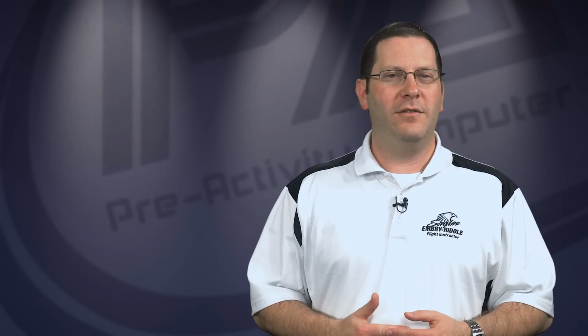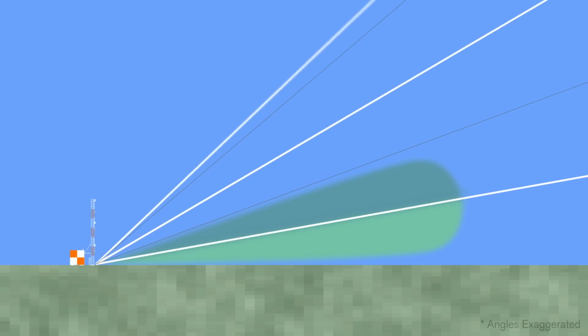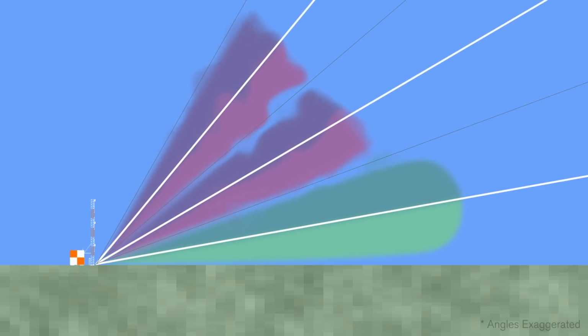Glideslopes are normally usable up to a distance of 10 miles. The Glideslope antenna creates mirrored transmissions of the true Glideslope, which produce false signals above the actual Glideslope, with regions of no signal in between. That means with a standard Glideslope of 3 degrees, the transmitter will produce the real Glideslope at 3 degrees and 2 false Glideslopes at 9 and 15 degrees.